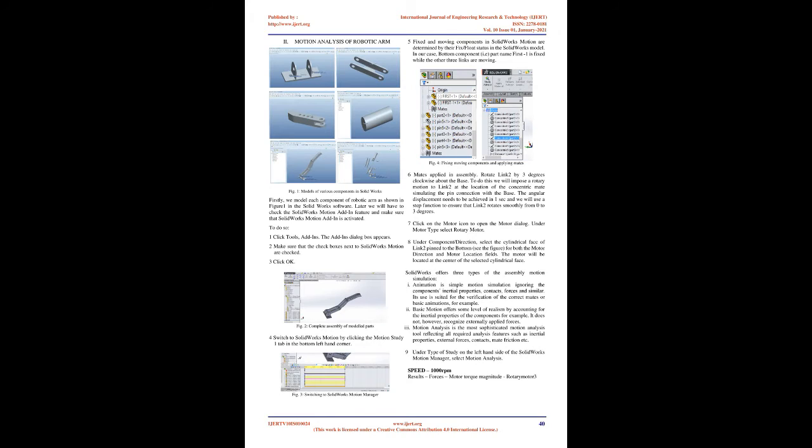5. The inverse kinematic model and robotic arm control was employed using LabVIEW and ARM microcontroller. LabVIEW uses parallel communication to transfer joint angles of the robot arm to the ARM microcontroller. The ARM microcontroller uses 5 PWM, pulse width modulation, signals to regulate the robot arm, which was equipped with servo motors. The robot arm is ideally controlled manually through the LabVIEW GUI, Graphical User Interface, control.